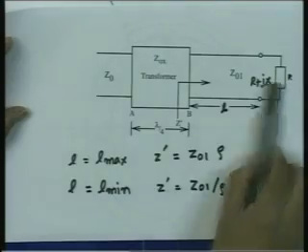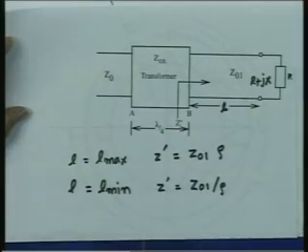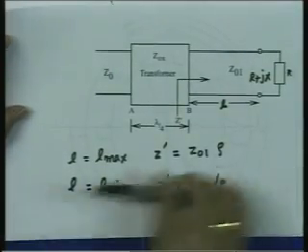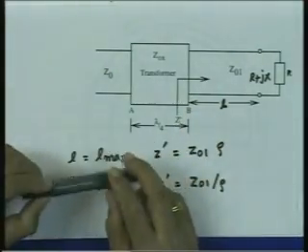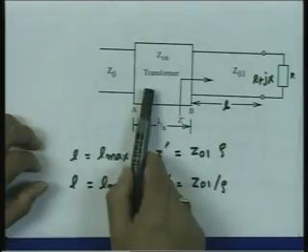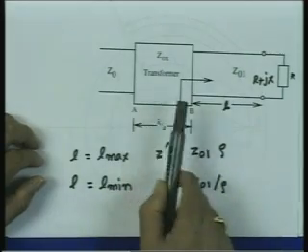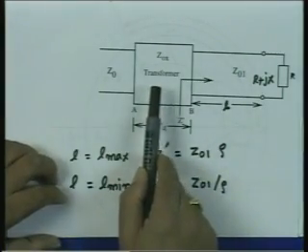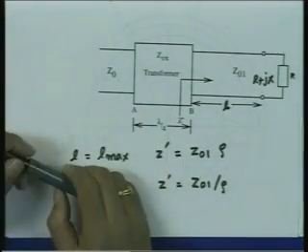So, this technique, the quarter wavelength transforming technique, can match the impedances even from complex impedance to a real impedance. So, this technique is used in practice in many applications. However, one would immediately note this technique has a biggest drawback, and that is you require a unique characteristic impedance for this transforming device.